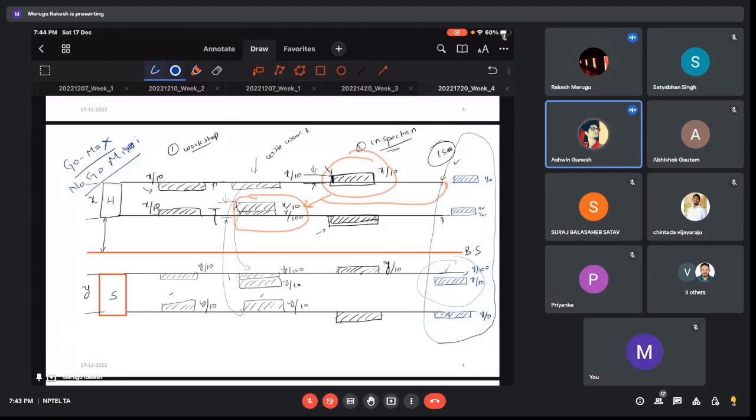For workshop gauges, for the no go, we don't have any wear allowance. Workshop no go gauges, of course, we don't have to, because it will not enter the product. So there will be no wear. That's the concept. Very rarely it enters.